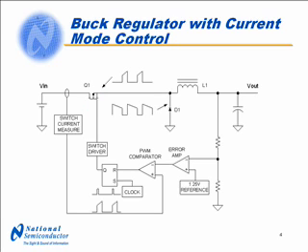It can be seen that there are quite a few steps that need to be accomplished each period. The minimum time required to complete these steps creates a minimum controllable on-time or duty cycle. For large step-down applications with a large input voltage and a much smaller output voltage, this minimum on-time can present a problem. The biggest challenge when designing for minimum on-time is the design of the current measurement circuit. We'll talk more about this in the following slides.